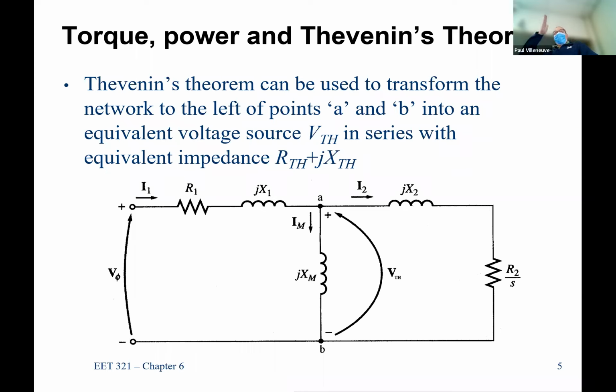A variable frequency drive takes input AC power, converts it to DC, and then outputs an AC electrical frequency, and you have unlimited control over that. You could run that down to 1 hertz, or if the drive is capable, up to 2000 hertz. So you could change your synchronous speed to whatever value you wanted it to be. And then correspondingly, you're going to increase the speed, which usually, not always, but usually increases the load demanded on something. So again, our mechanical engineering friends are the ones that are going to increase the load demand on our system.